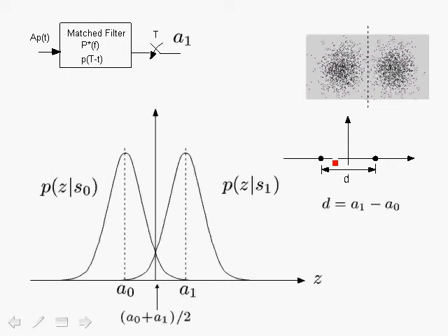And sometimes, even though we sent a 0 corresponding to a -1 symbol, the noise could be such that it gets closer to the side where the actual signal corresponding to a +1 was sent, and we can easily make the error of decoding that as a +1 even though a -1 was sent. That would cause an error in the digital communication link.